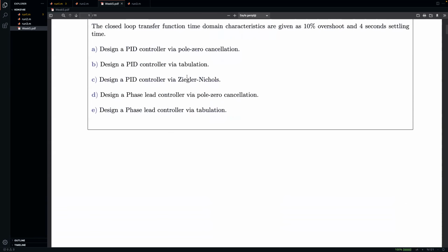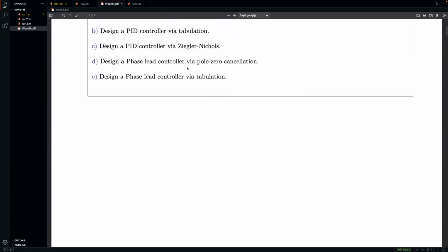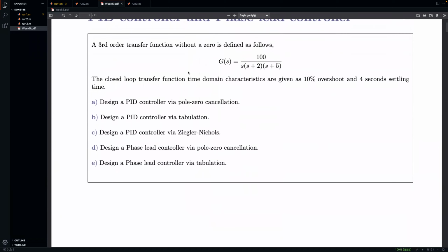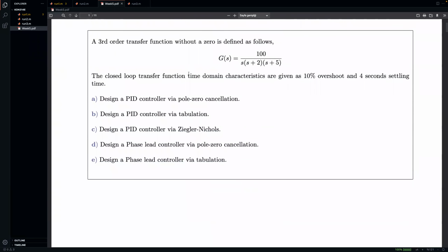So if you would design a PID controller that's not canceling its own pole, then you would get basically also ramp tracking. So this system would track its step input and ramp type inputs. Maybe not parabolic types. Therefore, you need to add another integrator, which is quite hard if you think about it, because we would have S cubed at the origin, which is not quite nice.